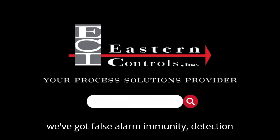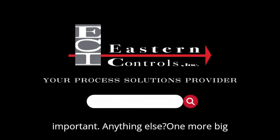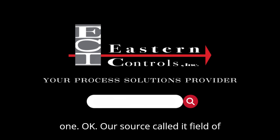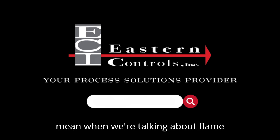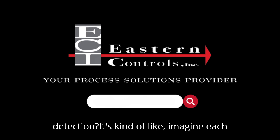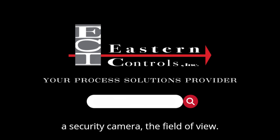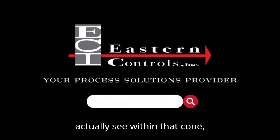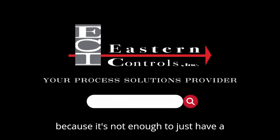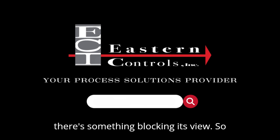Okay, so we've got false alarm immunity, detection range, response time, all super important. Anything else? One more big one. Our source called it field of view. Field of view, okay. What does that mean when we're talking about flame detection? It's kind of like, imagine each detector has its own cone of vision, like a security camera. The field of view is basically how much that detector can actually see within that cone. Because it's not enough to just have a detector that can see a mile away if it's pointed in the wrong direction or if there's something blocking its view.